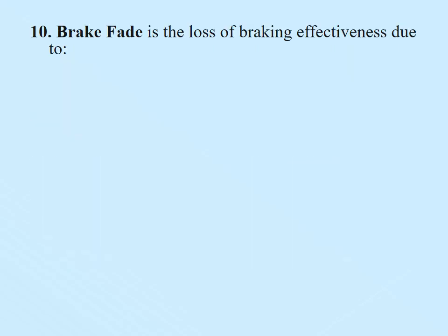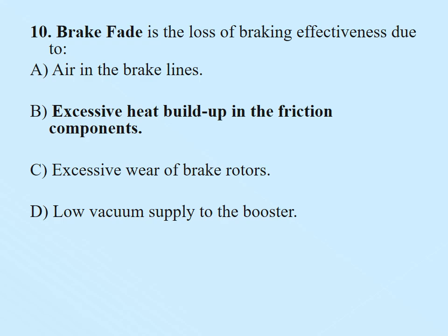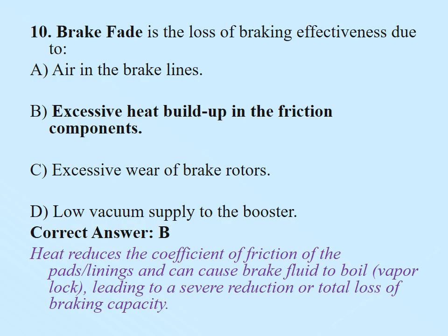Question number 10. Brake fade is the loss of braking effectiveness due to: A, air in the brake lines; B, excessive heat buildup in the friction components; C, excessive wear of brake rotors; D, low vacuum supply to the booster. Correct answer is B, excessive heat buildup in the friction components. Heat reduces the coefficient of friction of the pads or linings and can cause brake fluid to boil, vapor lock, leading to a severe reduction or total loss of braking capacity.